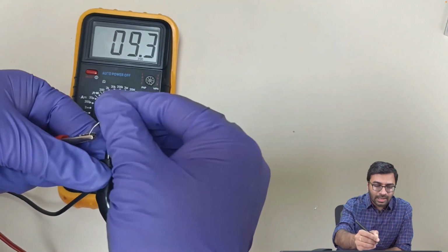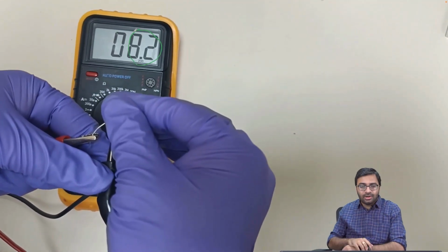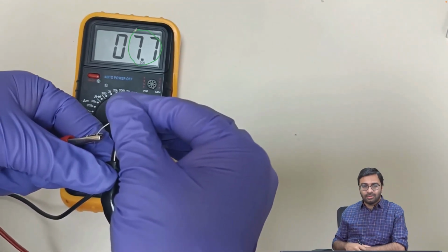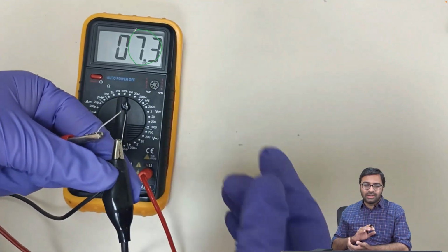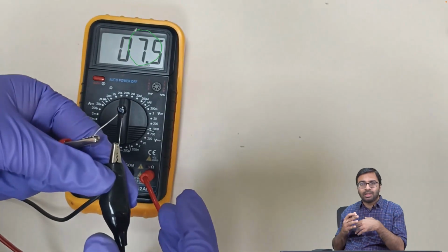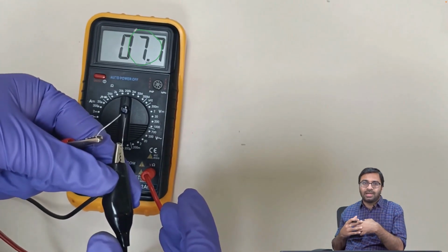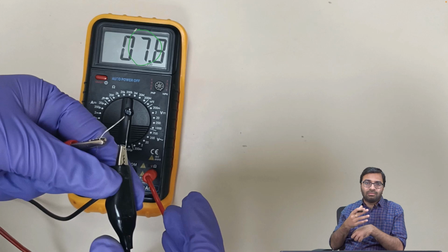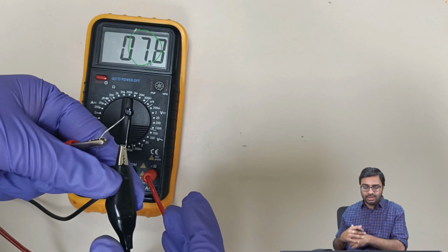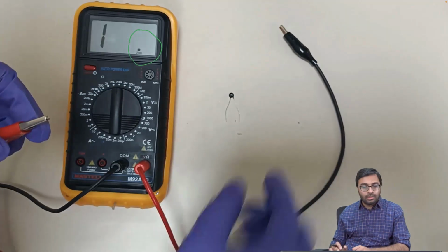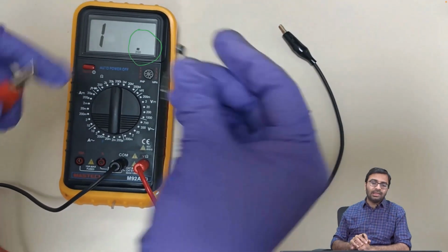Now you can see that the initial resistance is kind of 9 kilo ohm or so, which is the base resistance at room temperature. It should be around 10, but anyways room temperature varies. If the temperature is a bit higher than whatever is written in the specification sheet, you will find that the resistance is a bit lower than what is reported. So in this case the base resistance was 9 kilo ohm,